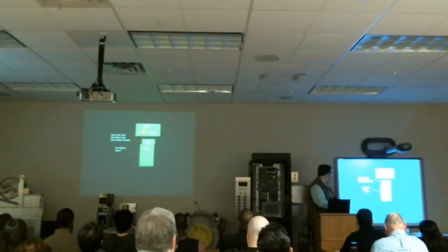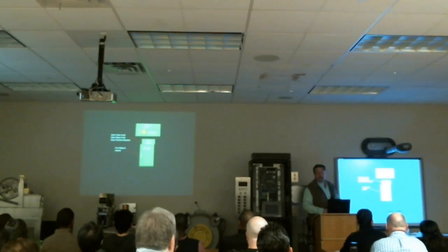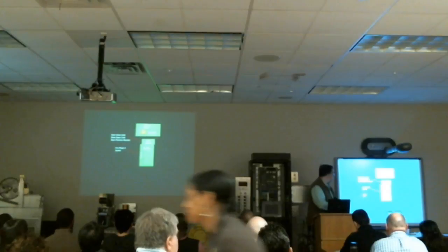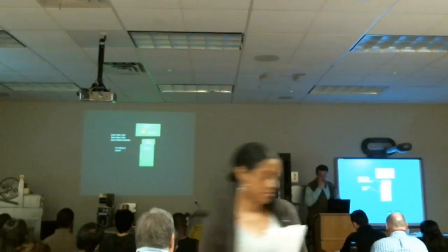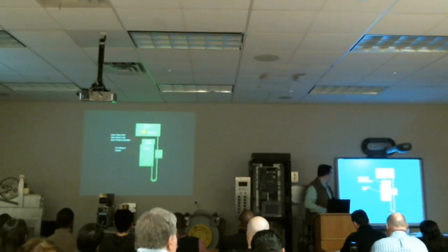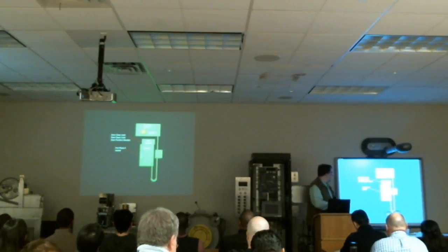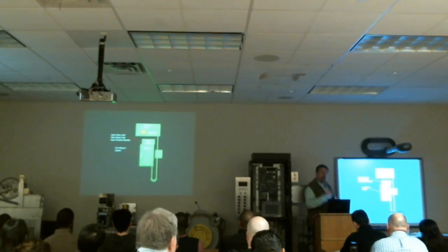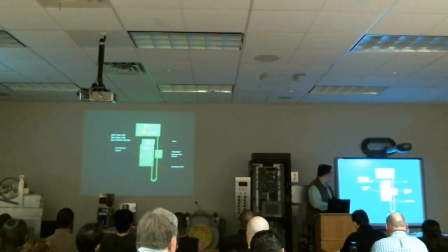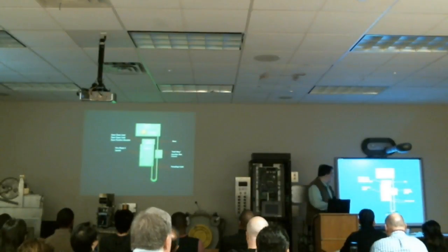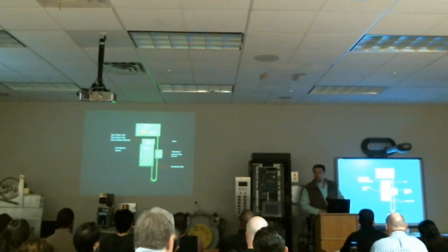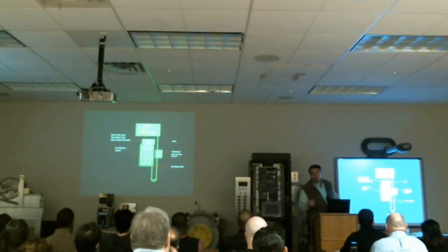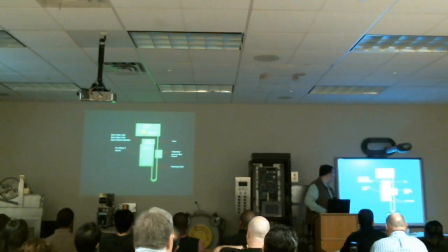We also have to monitor what? Fire phase 2, because in New York City they don't want door lock monitoring to be functional on fire phase 2 operation. So we need to monitor the fire phase 2 key switch inside the car operating panel. This is your traveling cable that goes from the elevator. And this is kind of a halfway junction box, if some applications have it, so that the signals will run back up to the controller in the machine room. So this is a traveling cable that sends the signals back up from the elevator to the control room, wherever it happens to be, either in the overhead or in the basement. It depends on the application.